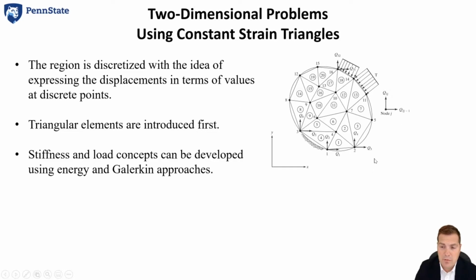So that would be revealed maybe through a mesh dependency study where you refine the mesh and see where your solution converges. It gets the same solution no matter what your mesh. And you have an idea of what kind of mesh resolution you would need. The other thing that's really important here is this numbering system.